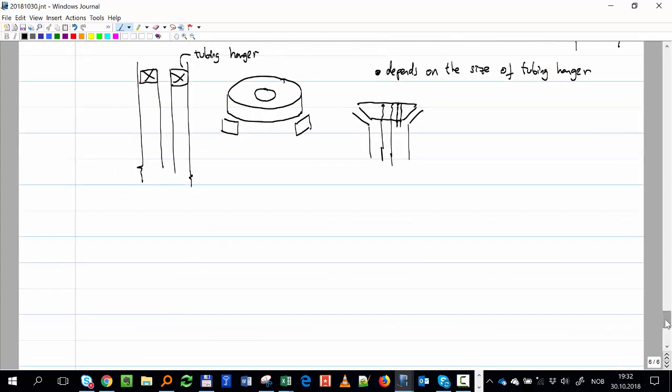Let's say, usually around 100 to 200 meters below the wellhead, you have a valve which is threaded in as part of the completion, as part of the tubing, and that requires a hydraulic line that is always kept pressurized. It's always keeping pressure on that valve, so it's always keeping it open.